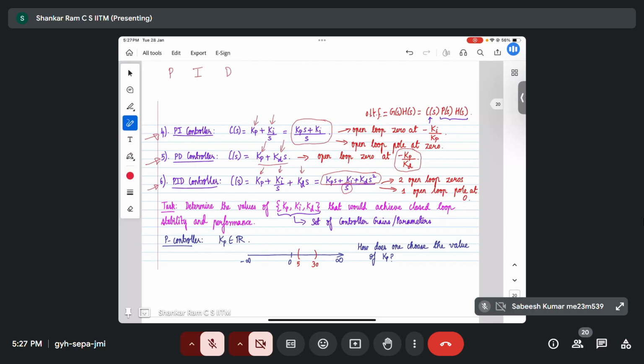Of course, one may ask the question, what about ID control? That could also be a combination. Even I and D are not used alone, because due to their action, they are always combined with the P controller, because the P controller helps compensate for any aggressive behavior by the I and the D controller.